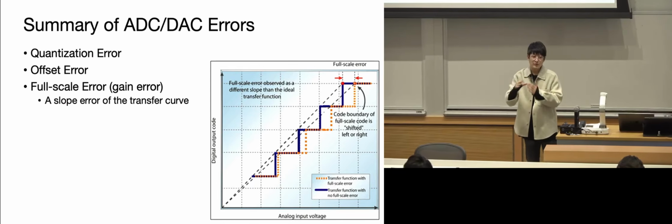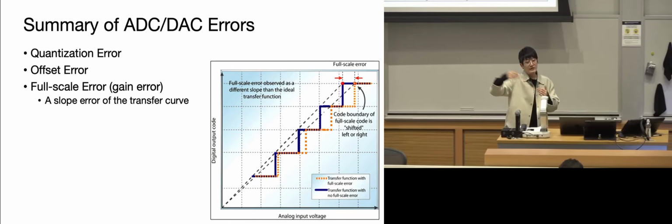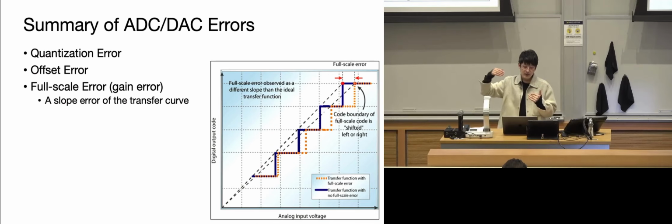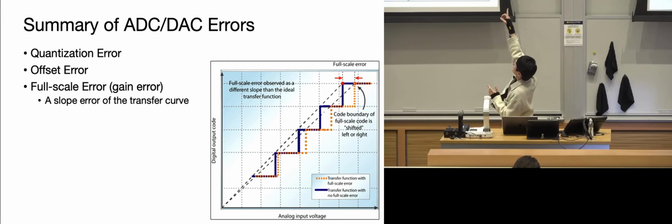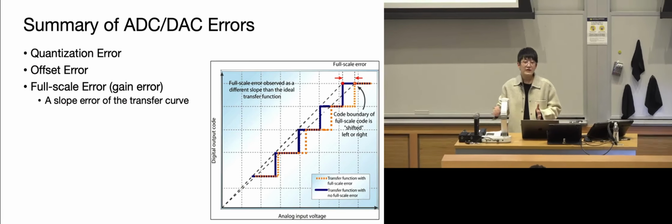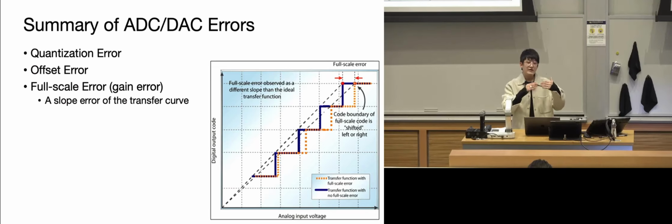So every step you have a proportional amount of error, and that accumulates to cause this. They call this full-scale error, or gain error. If you have to have the number, I don't think we test you on this, but on the top bit, that's the full-scale error you will be expecting. Again, this can be calibrated relatively easily with an internal known voltage reference to compare with the generated voltage, so that you can have a transfer function to shift the curve.